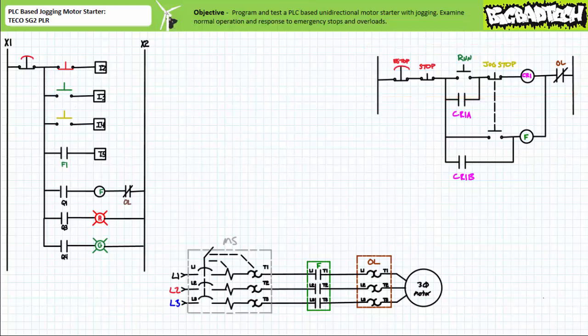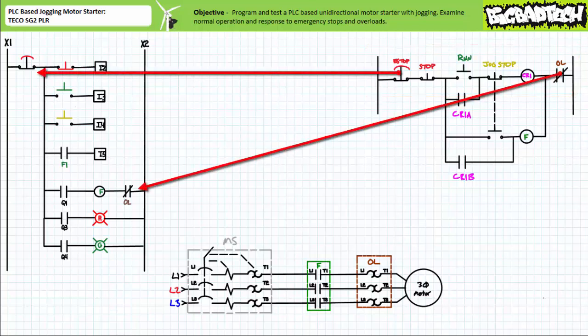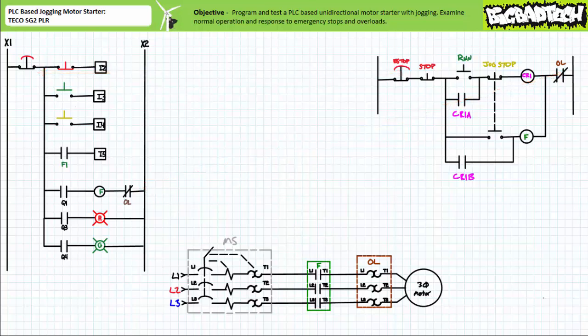Our task is somewhat simplified, however, by having the e-stop and overload already being hardwired into this system. However, we're still constrained by the available space. Add to our difficulties that our PLC-based implementation needs to effectively respond to overload conditions using real-world feedback using the F1 auxiliary contact, and the fact that we don't want this system to energize the F contactor coil and establish a holding circuit if the F contactor is ever physically forced closed.